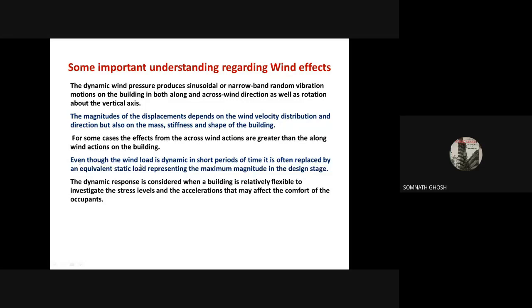Even though the wind load is dynamic, in short the period is short, it is often replaced by an equivalent static load, as I told you, but that is not correct. It depends on the time period of the structure, which you will get to in dynamic analysis, right?